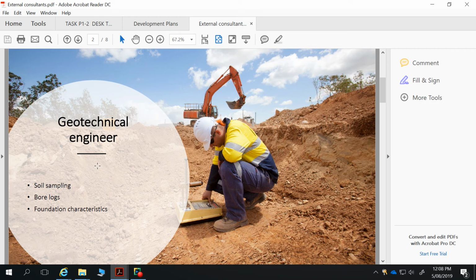But be aware of that as a constraint. And also on hilly sites, that is a massive constraint, because you can't do your soakage within, or, I can't remember the figures, but once the slope exceeds a certain point, you can't do your dispersal just with sprinklers on the ground. So you've got to dig trenches, build retaining walls, all this sort of stuff. But retaining 200 square metres of land is a big cost. Important to be aware of those things and think laterally about all that stuff as well.